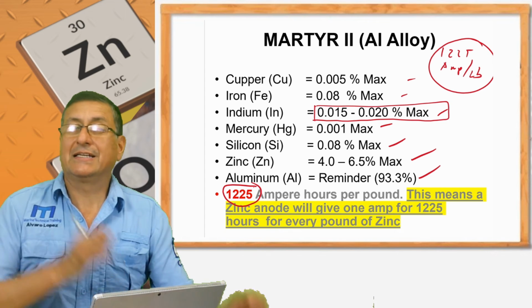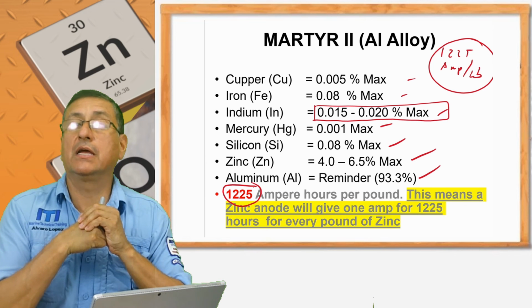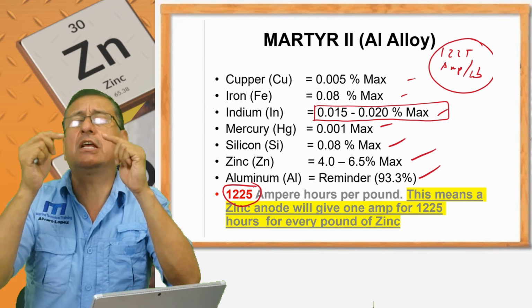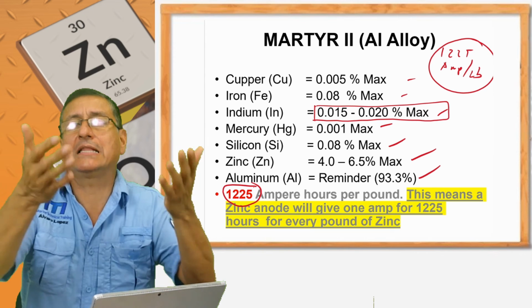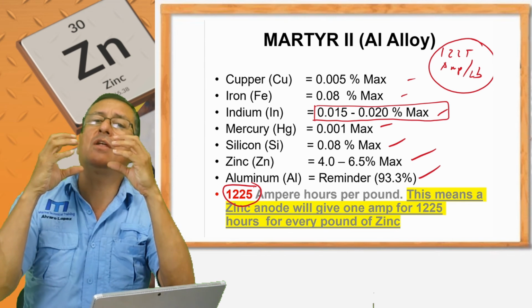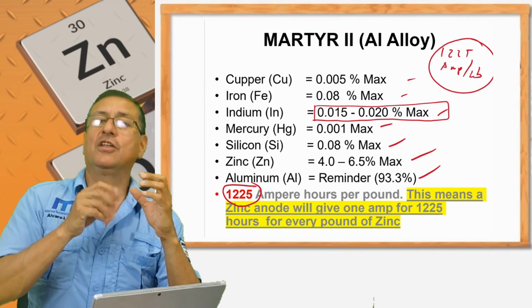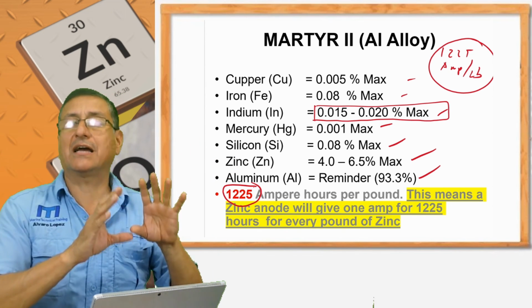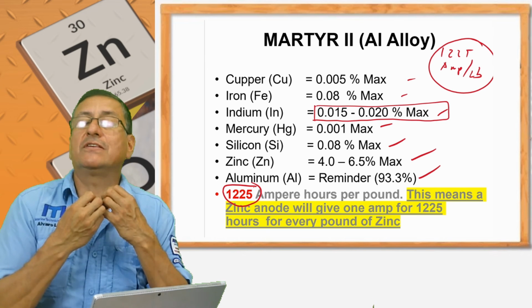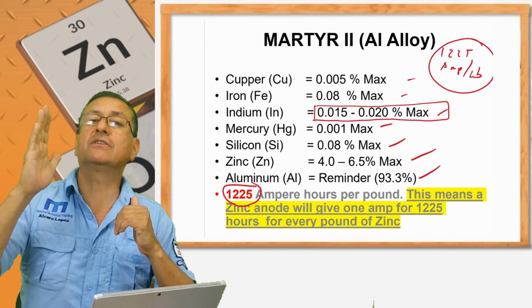What is the meaning of that? The intensity is higher with this aluminum alloy, and the protection is better. The potential difference is higher. When the potential difference is pretty close, that anode is not working because it's the same level of energy. You need an anode with a lower level of energy in order to produce a high arc, in order to erode easily the sacrificial anode and protect the metal. This is the secret. Select a sacrificial anode with a lower level of energy in order to create a high potential difference.